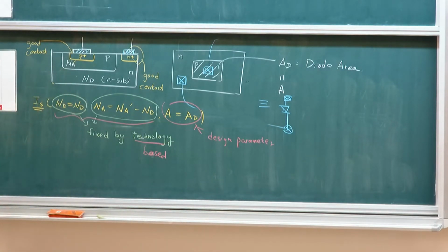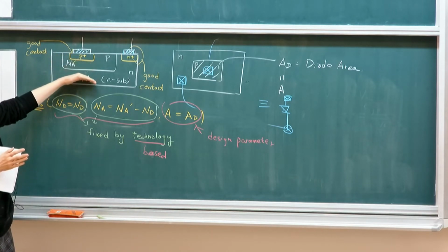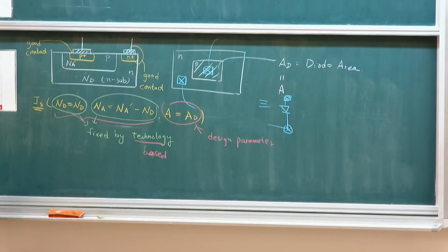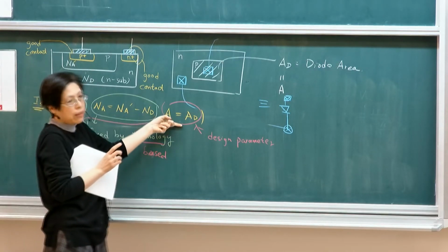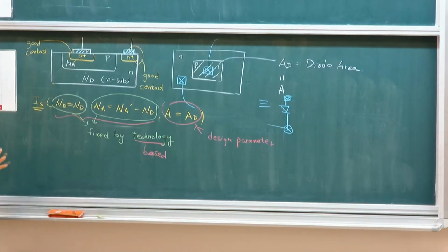So this is one of the limits of this type of device, typically referred to as a bulk device, because the current is flowing through the substrate. With this type of device, you only have one design parameter to design your IS. But if we look at two-dimensional devices such as MOSFETs, you then have two-dimensional freedom for designers.